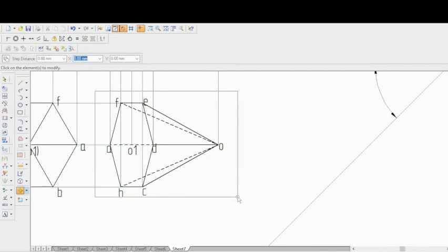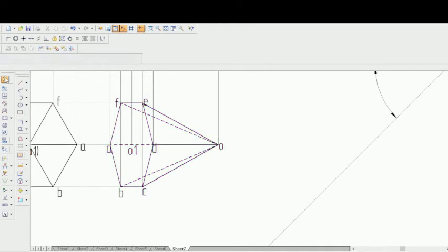Another thing is, when you're selecting like this, the center lines, this O1, will not get selected. So you can use the split option and retain those center lines also, center O1, so that it will be much easier. Now let's use the control key and select each line.